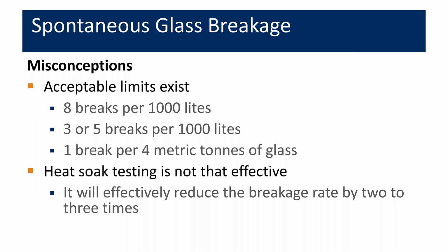The fact of the matter is that heat soak testing has been shown to convert about 99% of all deleterious nickel sulfide inclusions. So in other words, the estimated reduction in breakage rate is about 100 times. And also, more significant published research on heat soak testing has shown that the process virtually eliminates any concern about spontaneous glass breakage, and that's 2018 research.